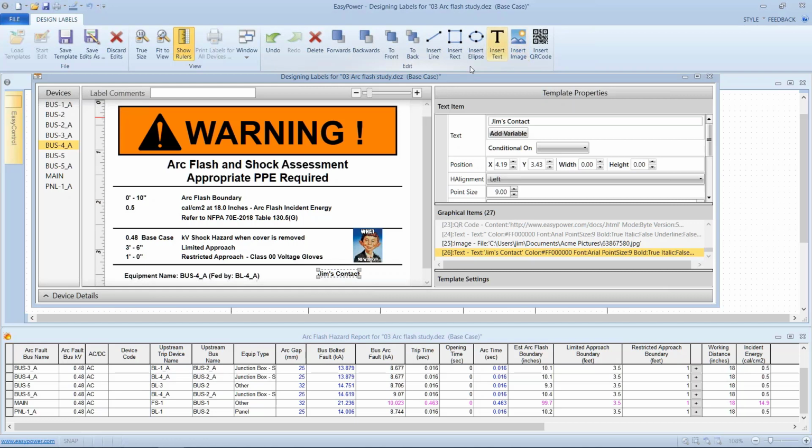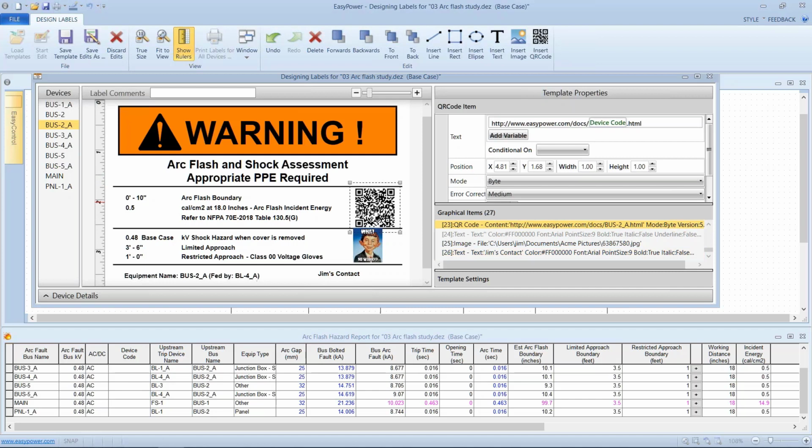Okay, now this brings me to, and as you see, as I scroll through these buses, I have this QR code showing up. So the request was, if my electricians go by this bus or this panel 5 times a day, they're not even going to look at it if the information hasn't changed in 5 years. So I want them to be able to scan the panel or the label on the panel and record the voltage and current that they read on the panel. So effectively a manual data acquisition system.